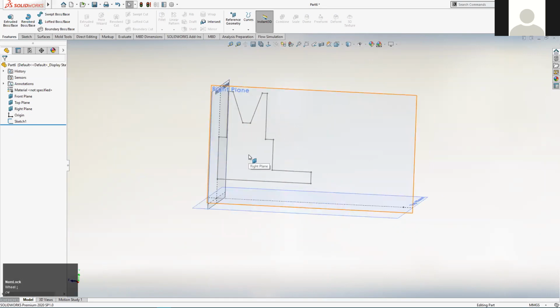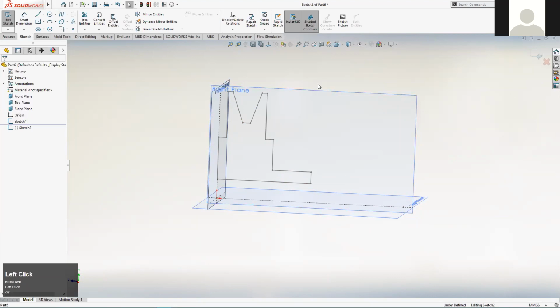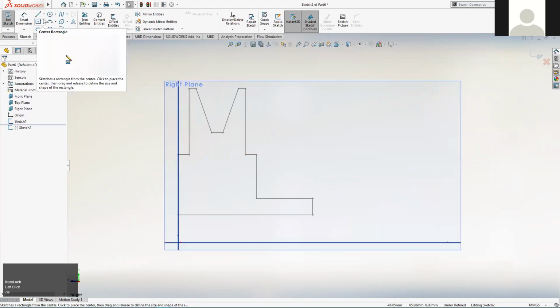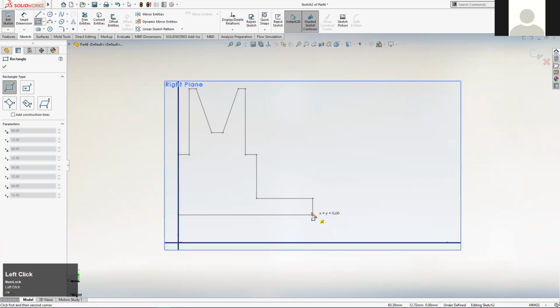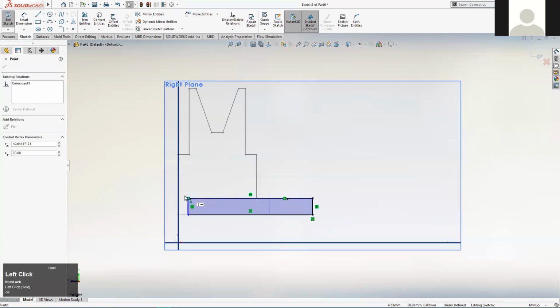So the reason I've retained that is so that my 3 sketches, or possibly 4 sketches that I'm about to create, can be quickly just locked onto this sketch. So if I was doing this for real, I wouldn't do it this way. It's just to speed the process up as we're doing it now. So what am I going to do? I'm going to create an initial revolve. I'm going to sketch on this plane, and then I'm just going to create a rectangular shape. And as I say, if I was doing this correctly, I would be putting all the dimensions in for this rectangle. But as it is, just to speed things up, I'm just going to lock it onto this sketch that's in the background because I happen to have that.